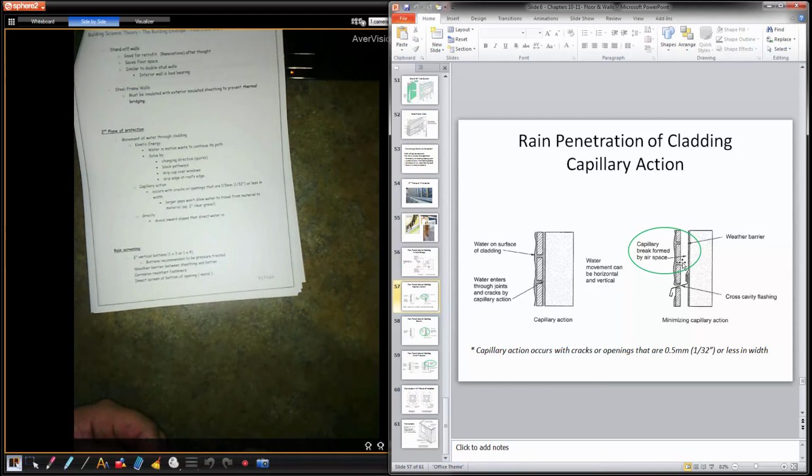So water would flow down here. If we don't have this metal bracket, it could just kind of curl and stay. But you see how, here's your drip cap. Water will follow that drip cap, gets to the edge of it. It wants to curl around, but there's nothing to grab onto. There's a gap there, so it falls. So if that's making contact, it would just curl back around onto that material and possibly go uphill.